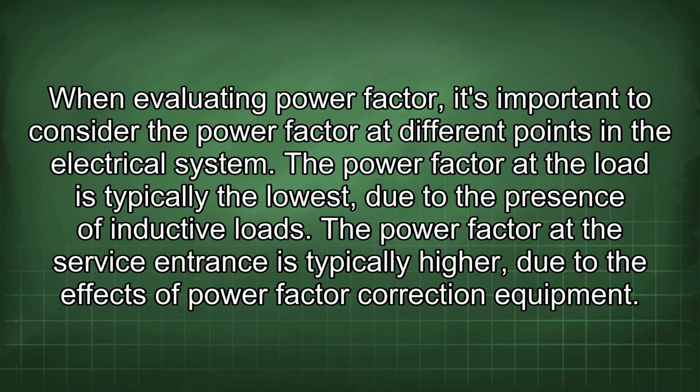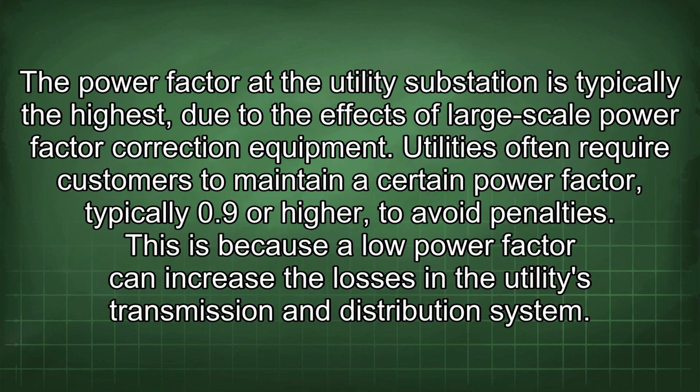When evaluating power factor, it's important to consider the power factor at different points in the electrical system. The power factor at the load is typically the lowest, due to the presence of inductive loads. The power factor at the service entrance is typically higher, due to the effects of power factor correction equipment. The power factor at the utility substation is typically the highest, due to the effects of large-scale power factor correction equipment.